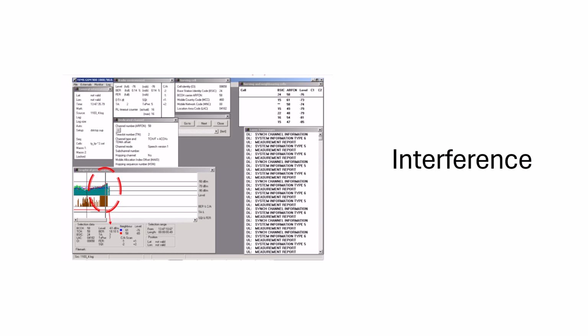Example scenario: suspecting external interference in GSM 900, in TEMS set up a frequency scan from 935 to 960 MHz, typically the GSM downlink band. Let the scanner sweep through all ARFCNs in this range. Examine the resulting spectrum graph.